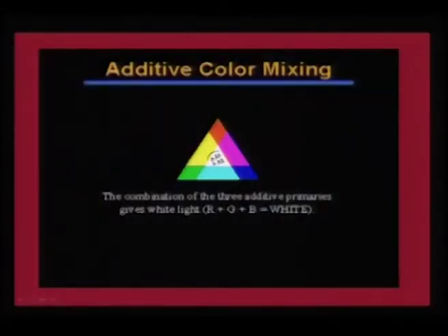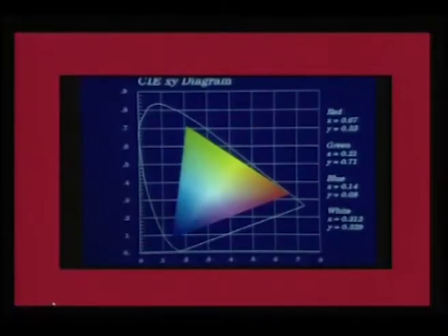So, the color coordinate that is recommended for pure white is 0.33, 0.33, which is defined by a CIE diagram. This is an international standard, called the CIE xy diagram. You can plot the components of blue, red and green in a 2-dimensional plot, and this way your x-axis value and your y-axis value will tell you where exactly you stand. For example, white should necessarily come here.